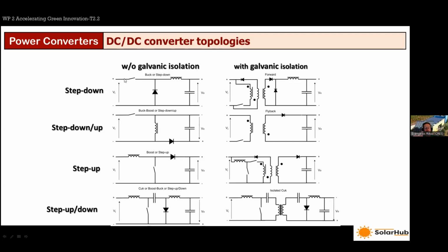Okay, and it operates on the premise that the input and the output voltages are constant but different. You will have an output voltage that is lower than the input voltage. So once you close this switch, there is a current flow from the input through the inductor, the capacitor, and the load, if there is a load here. And so there is an amount of energy stored in the inductor and the capacitor.